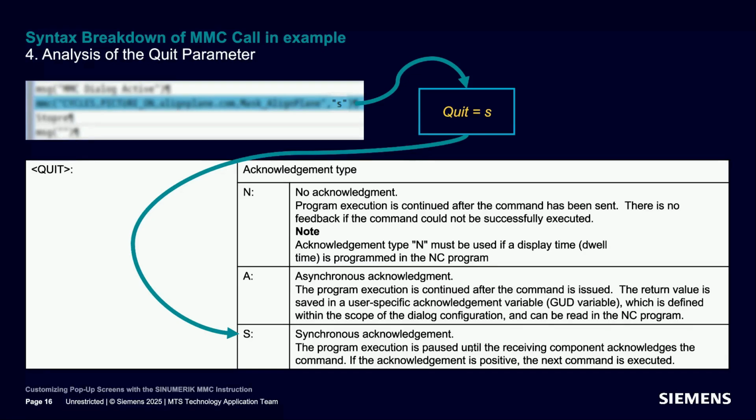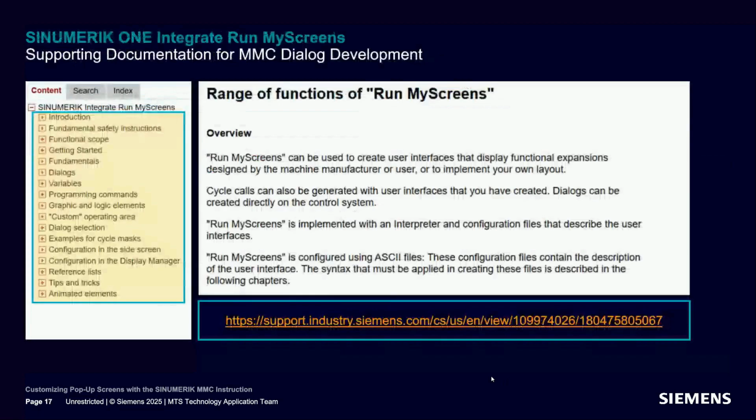In the standard Siemens cycles, for example, we do invoke the MMC instruction if called for in the cycle 150 associated with the measuring cycles. And in that case, we would have a cycle start to clear the MMC dialog rather than hitting the button within the dialog. So it's up to you how you want to do it. This is just how that example was configured.